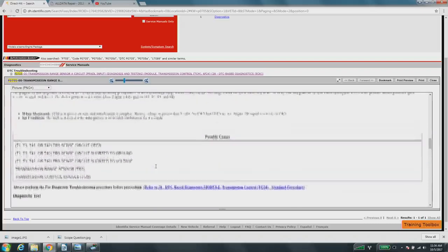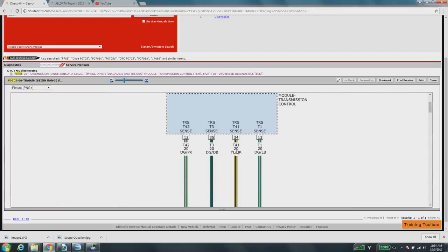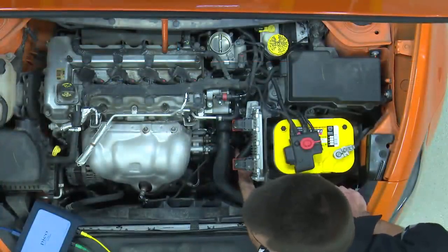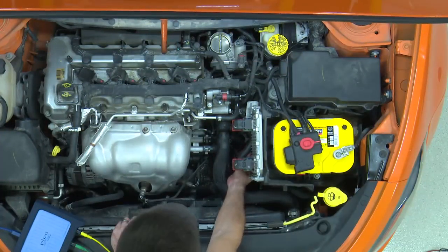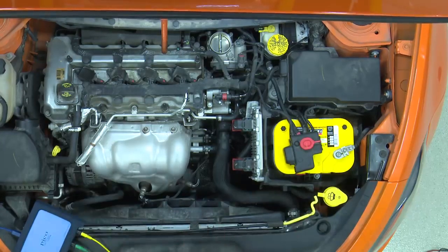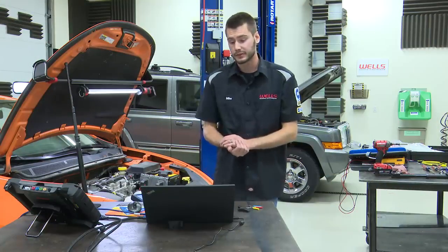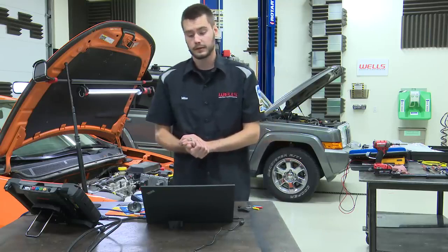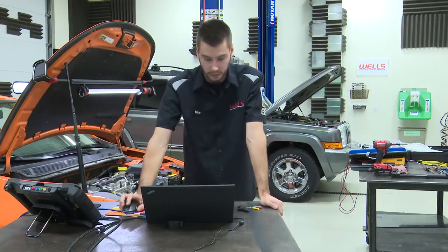Now I have another problem with this, and that is the fact that I have wire color labeled out here as T41 being yellow and black. Well, I know you guys can't see this connector down here. Well, maybe you can. I don't know. It's probably hard for you guys to see. We might be able to see it once I get everything out of the way here. But I don't have a yellow and black wire in this connector down here. Okay, so again, be careful with wiring diagrams. I'm going to go with trusting that pinout for back probing this thing, and hopefully we are correct.